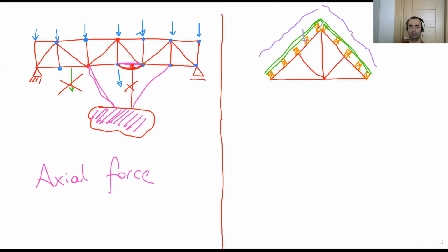What we said in the sketch at the left-hand side, we said we only apply loads to joints. But here, as you can see, there are some purlins at the midpoint of the members. There's no joint here. Here, here, here, here. These points are problems, but still, especially in truss systems, you can see this system.